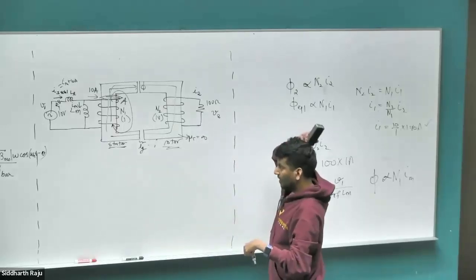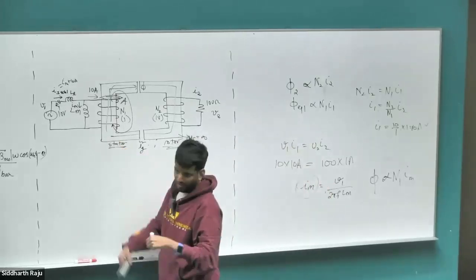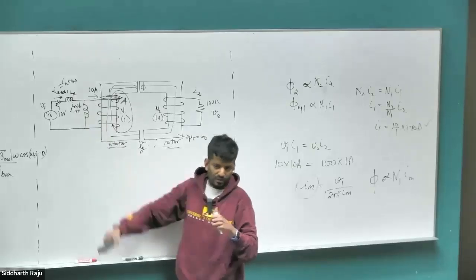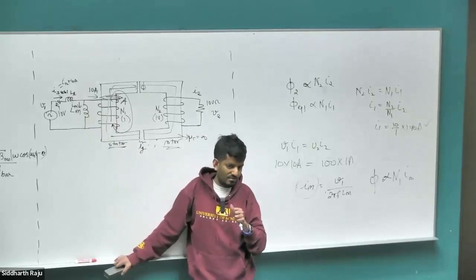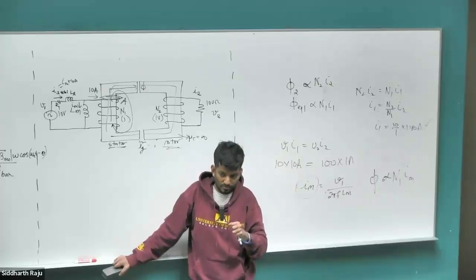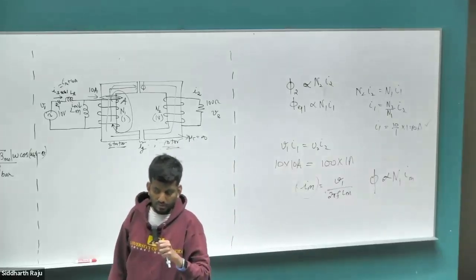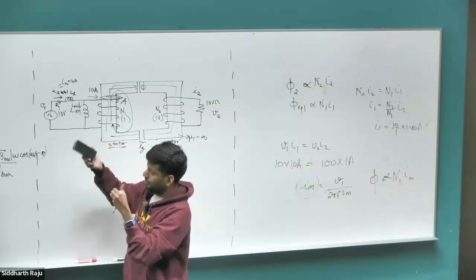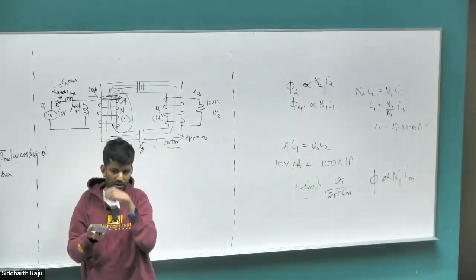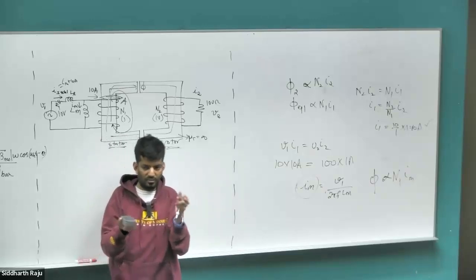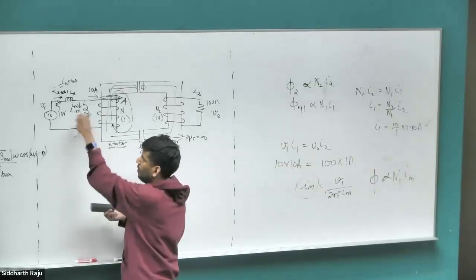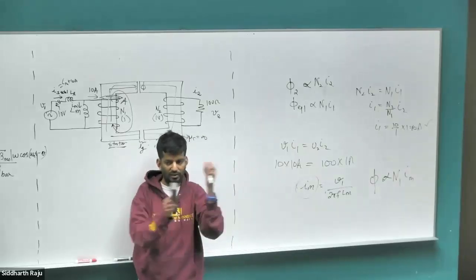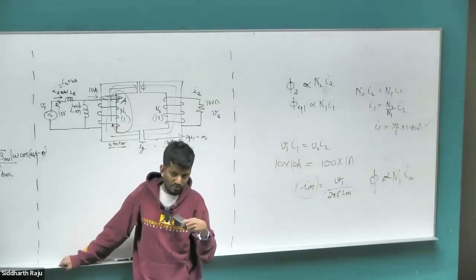LN. Okay. Why do I put it on the left side and not on the right side? In all the equivalent circuit transformer diagrams, I've always seen it on the left side, but not on the right side. Because it occurs before the core? It doesn't occur before the core, it occurs at every single point on the winding. Right? We are using this bulk model for inductances, but it's actually the wire going across the core. Every single point equivalently drops some kind of inductance, some kind of resistance. It's like a distributed pi model kind of. Right? So it is not like one single block I have, and then all of the inductance is lost there, and then we have the remaining. So why do we put it on the left and not the right?